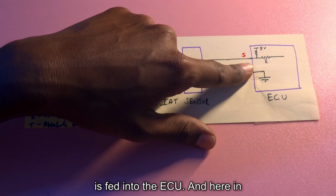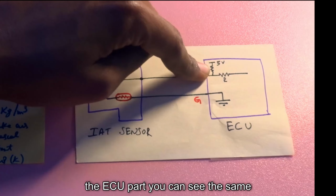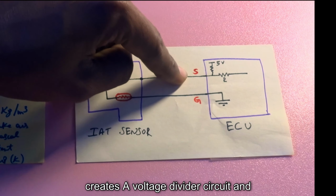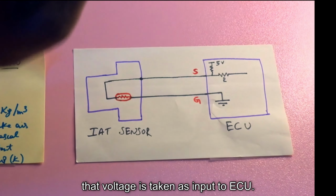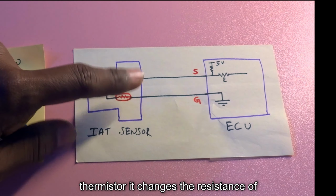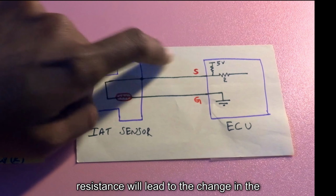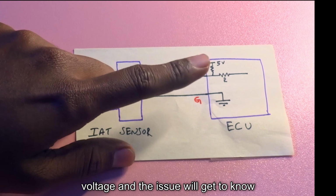and that change in resistance is fed into the ECU. And here in the ECU part you can see the same wire is pulled up to 5 volts. This creates a voltage divider circuit, and that voltage is taken as an input to the ECU. As the intake air flows over the thermistor, it changes the resistance of the thermistor, and that change in resistance will lead to a change in the voltage, and the ECU will get to know the temperature of air.